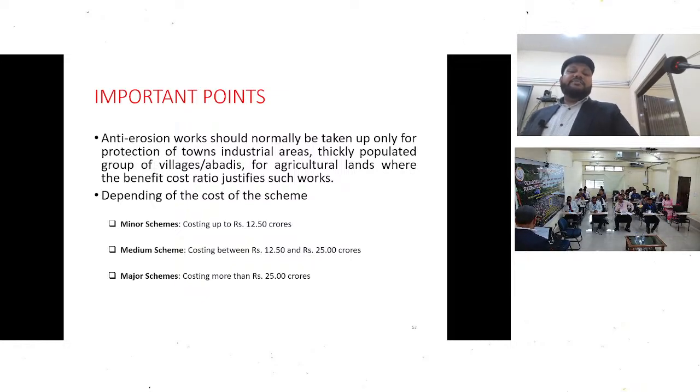And if it is a medium scheme of 12.5 crore to 25 crore, then investment clearance is required from CWC, or from the Ganga Flood Control Commission in the Ganga Basin. Or if it is more than 25 crore, then investment clearance is required from a committee headed by the Secretary, DOWR, RD and GR, Ministry of Jal Shakti.